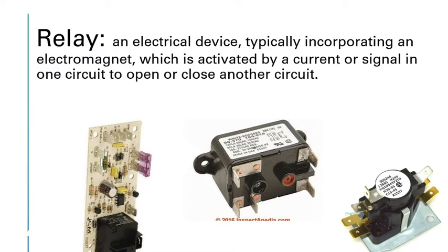The rest of this board is a time delay or extender, so it either keeps the fan on for a longer period of time at the end of the compressor cycle, or it turns it on slowly, so it gives time for the heat exchanger to heat up or the coil to cool down before it starts blowing air.